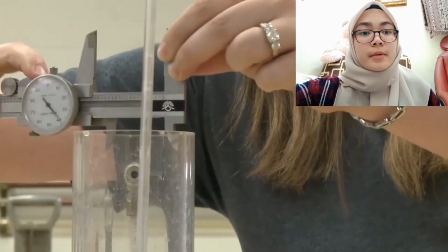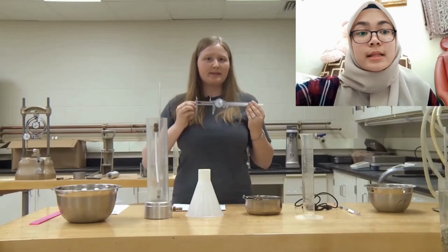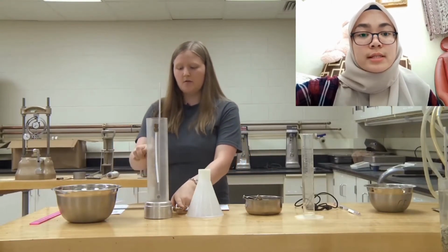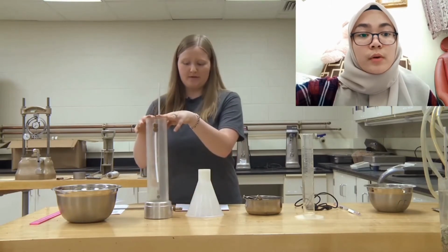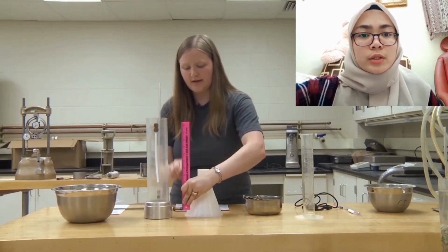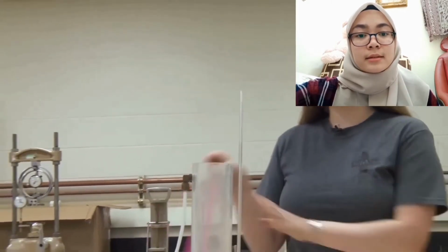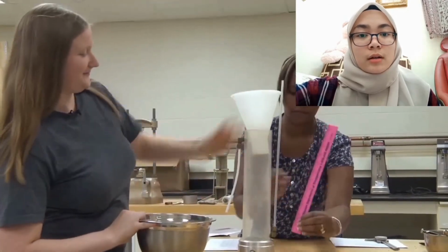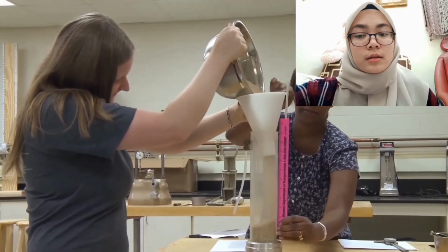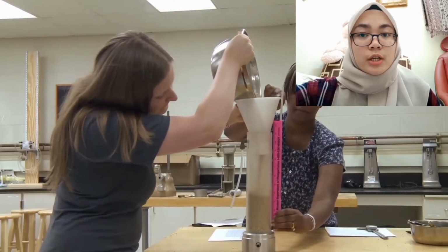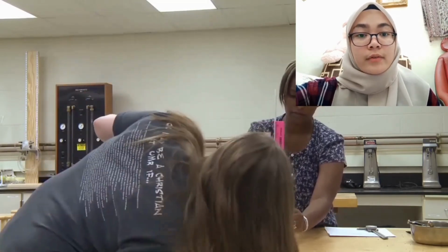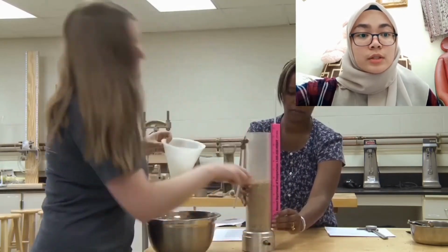According to the ASTM regulation, the amount of soil needed from the inlet point to the top of the sample is 2 times the inner diameter of the permeameter, so 5 inches from the center point up to the top of our sample are needed. In order to place the specimen within the permeameter, hold the ruler, then pour the sand in with the funnel. Stop and shake the permeameter a bit to make sure the level is correct and measuring correctly. Have a 5-inch mark from the center of the inlet to the top of the soil sample.